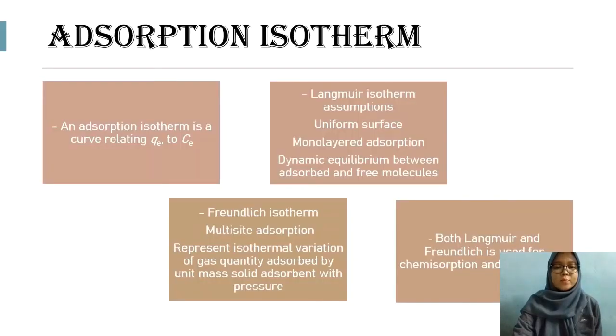Moving on to the next part, the adsorption isotherm. Adsorption isotherm is a curve relating the equilibrium concentration of a solute on the surface of an adsorbent, qe, to the concentration of the solute in the liquid, Ce.